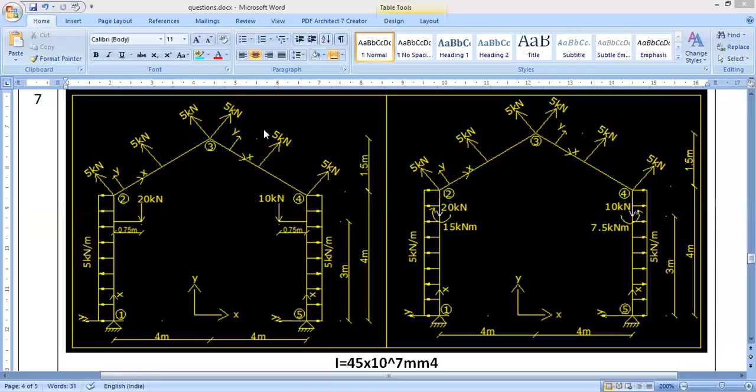So let us go to Staad Pro and see how to analyze this type of gable frame. This is a typical problem of the industrial frame. This problem can be dealt with as the forces that occur on the members due to suction pressure, which is exerted by the wind load. And you can see the supports are hinged supports.